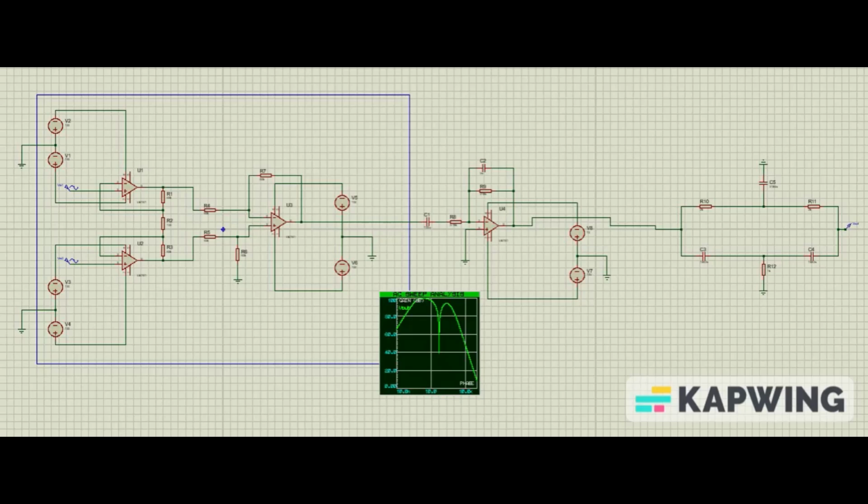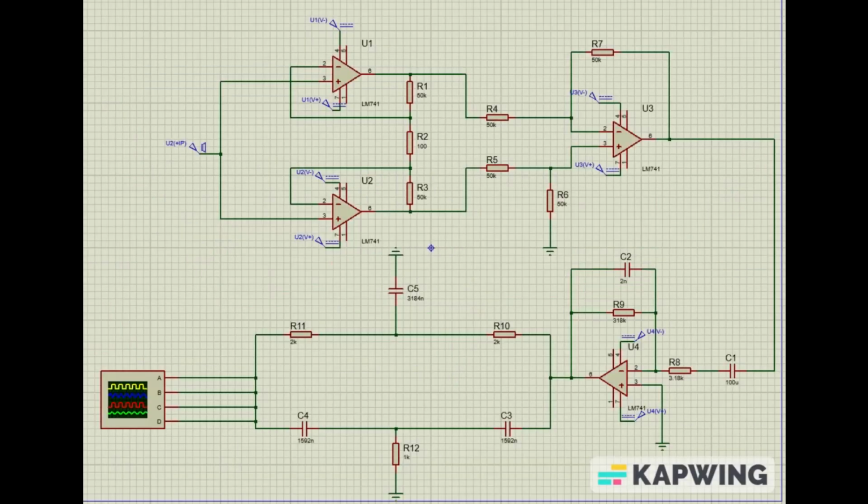Usually, amplification is done before filtration. So, as I mentioned earlier, the instrumentation amplifier was placed at the beginning. The band-pass filter amplifies the signal further, so it was placed second, before the notch filter, which only filters out a specific frequency. The entire circuit was also tested using an AC sweep simulation, which produced expected outcomes, including amplification within the range of 0.5 up to 250 Hz, except for the 50 Hz notch range, which was filtered out as intended.